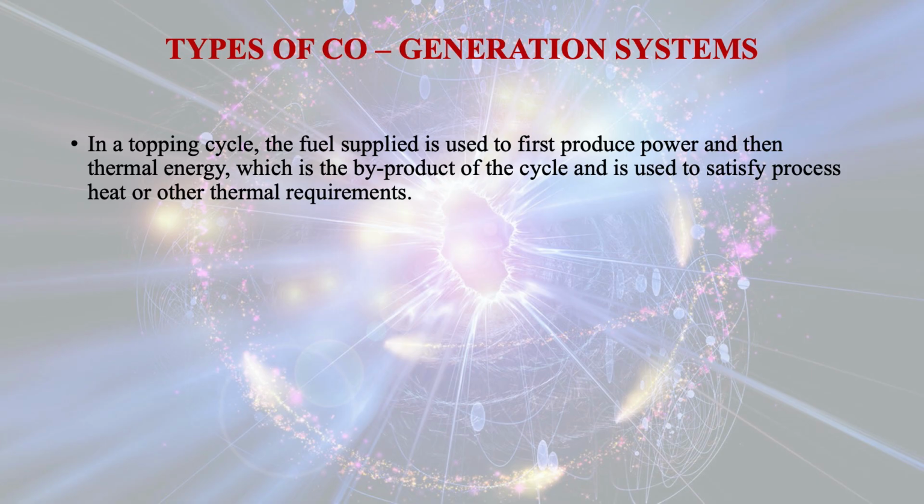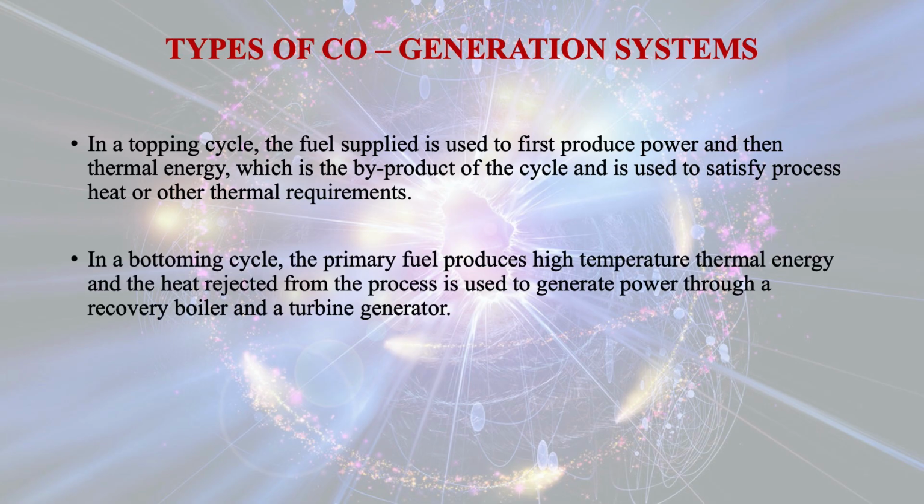This cycle is not an ideal cycle, as mixing in the feed water heater is not reversible. However, with a several number of extractions of steam from the turbine, that is bleeding, the mixing process becomes reversible and theoretically Carnot efficiency can be attained.